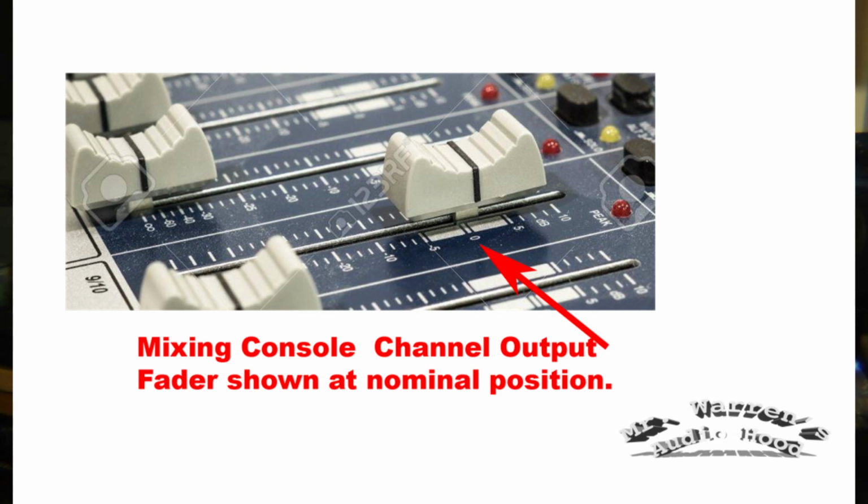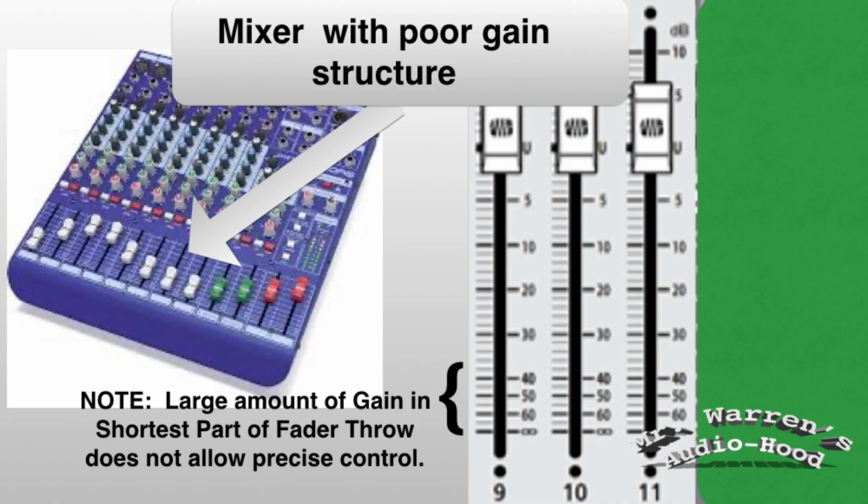While the goal in using a typical mixer is for the input channel faders to be set around nominal, some adjust in the course of the show, either slightly above or slightly below is not unusual. What you should not wind up with is something that looks like this. Typically, if I walk into a setup and see this, I know immediately the mixer was not gain staged correctly.